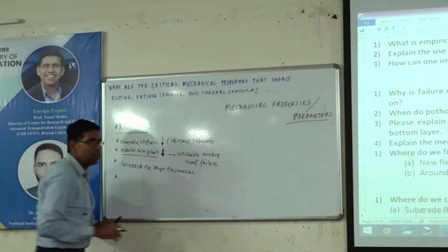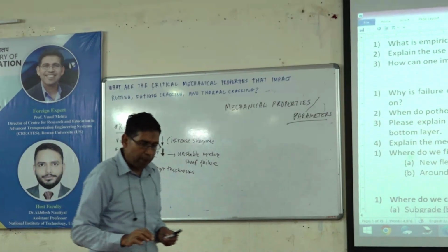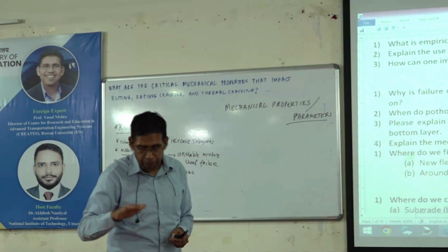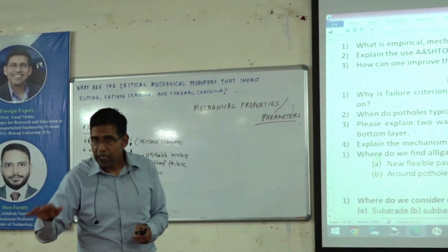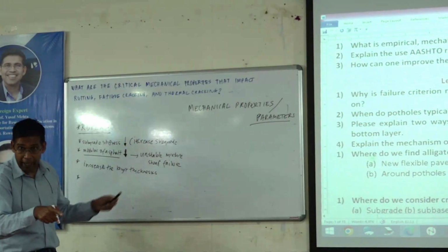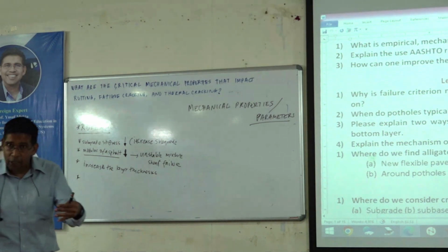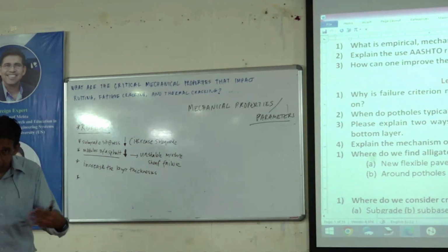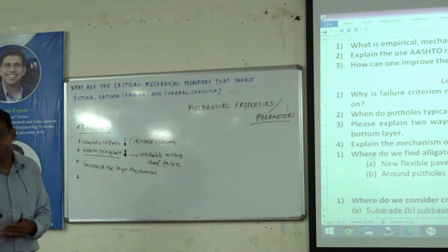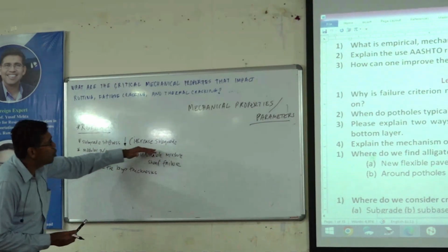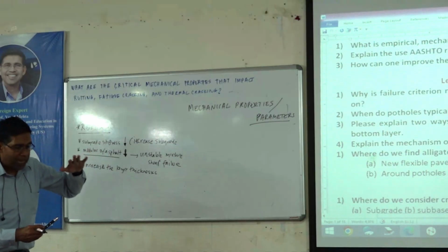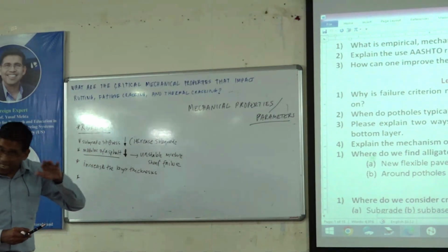But the reason why you don't want to talk about stabilizing the subgrade, and at least add the reason why I say that, is because at some point you're going to hit the natural soil, right? You're always protecting the natural soil. So if you talk about stabilizing the subgrade, that means you're taking the natural soil and it almost becomes like a sub-base layer, but there's another layer below that. That's a natural soil, right? So you're in effect protecting something else. So you want to stay away from any discussion about tampering with the natural soil, because that is assumed to be there, right?